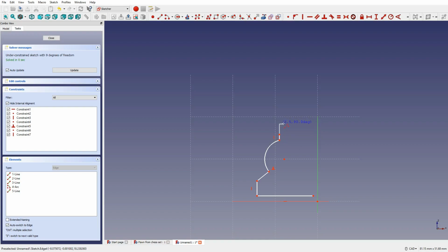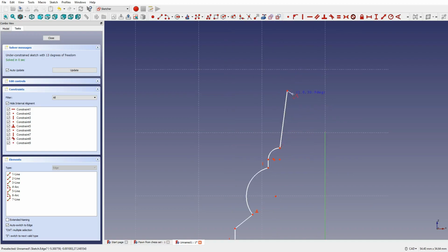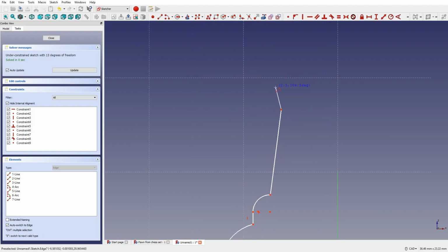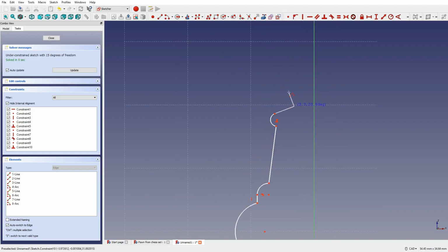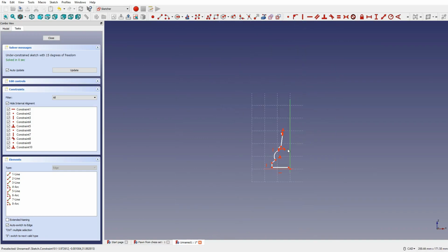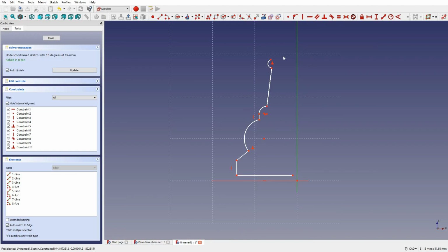Again, clicking the M button once, twice, three times to give me another radius tool, different to the last radius tool, and clicking like so. Then for this one I'm going to create just a general straight line, which gives me just the start. So this later on will have a tangent line here. I'm then going to click M, M, M, M again to give me back this radius tool. Click, and again I'm just going to right click to get rid of that line now, and right click again. So what I've done is I've just created the basic outline of this particular shape.